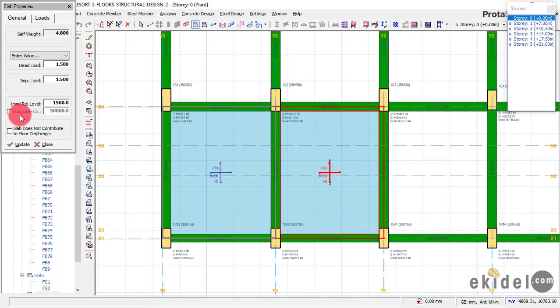Now this place that says subgrade, I'll leave it at 50,000 coefficient of subgrade. So leave this subgrade as default. But if maybe you want to change your subgrade, before you change it, you have to go and read the textbook that is written by this author. I've forgotten the author, but I'll try to remember before the end of this part 2.